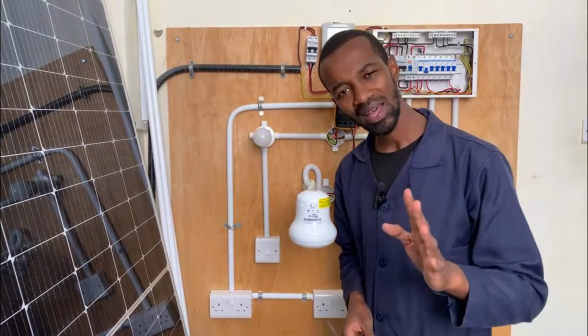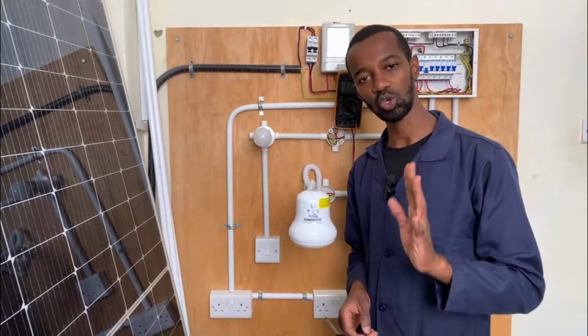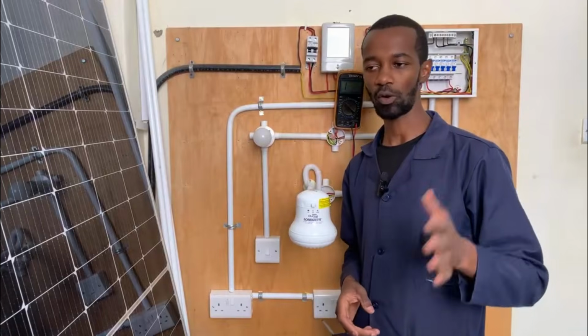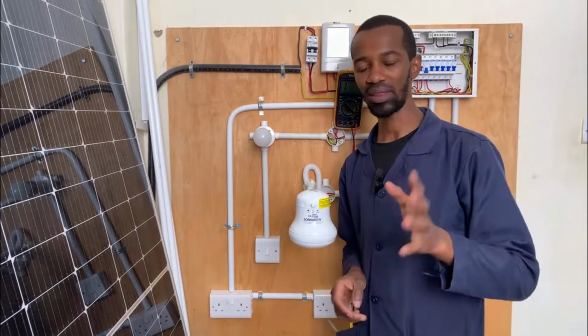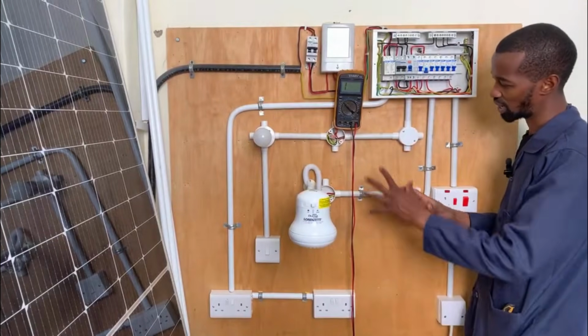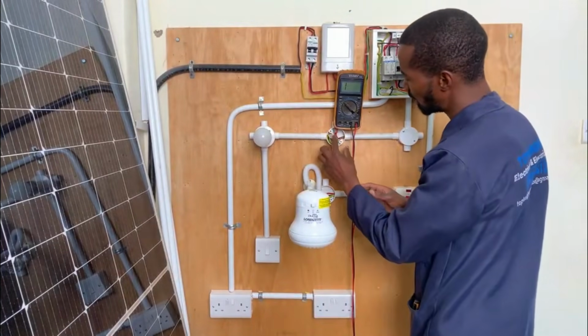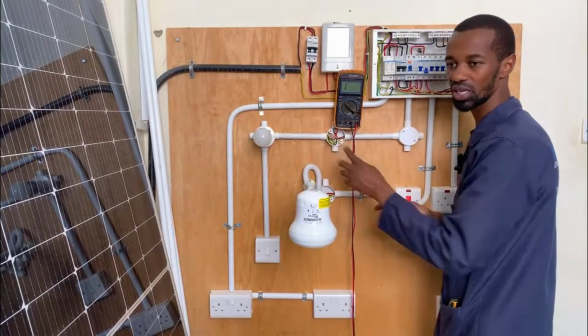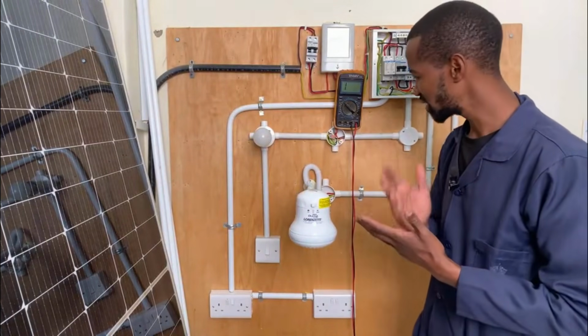You may power that MCB, probably the MCB was not faulty, and you are forcing it to turn on and it breaks completely. So please ensure that you first of all narrow down where the problem is. For us, we had a makeshift problem at this point here. But how will you arrive at this point? You go on isolating every circuit.